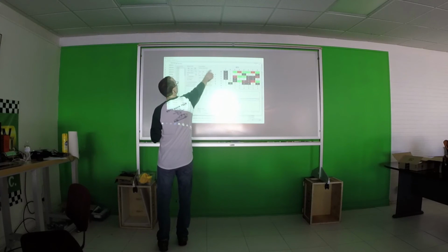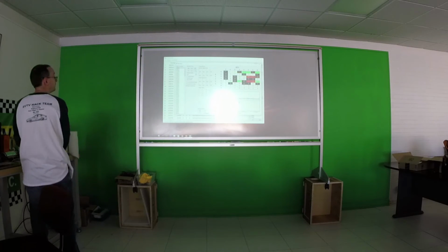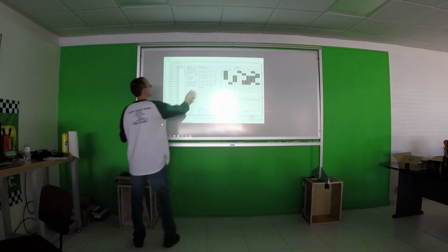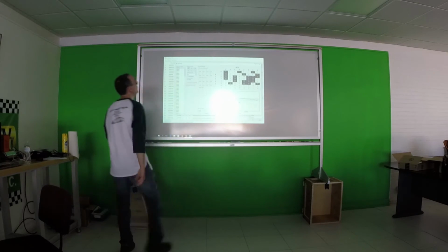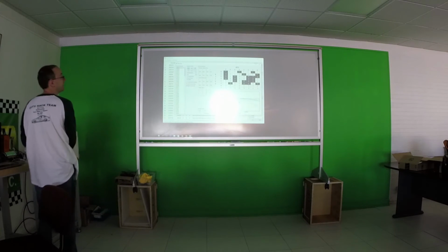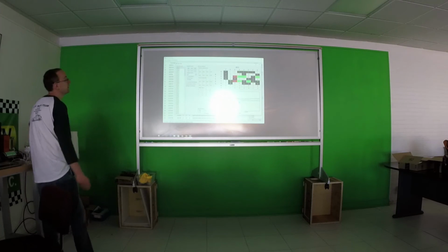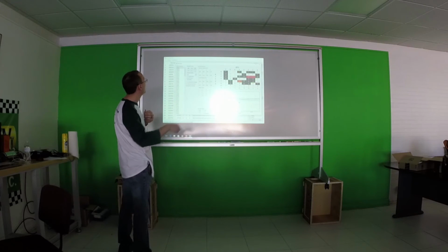That's according to this reference, which defaults to the very first frame in the capture. Can I change the reference? You can change the reference to anything you want. Or you can set auto-reference here, which will automatically, every time I play a frame, right before we go to the next frame, copy these values up here. So auto-reference will give you basically a delta of what bits changed from frame to frame. Now you're seeing just the bits that changed every time the frame updates.